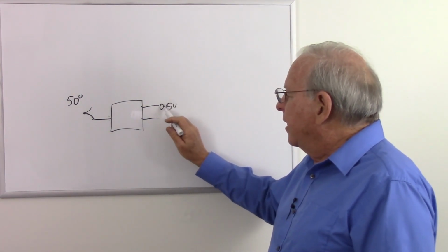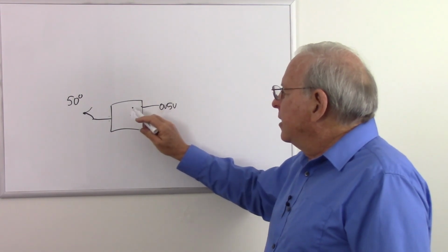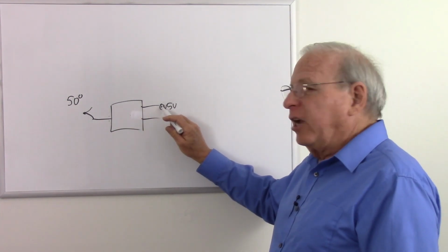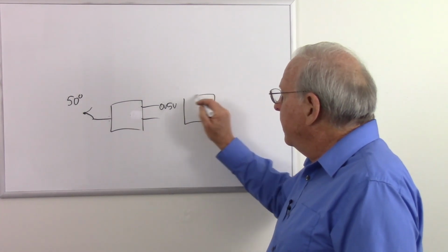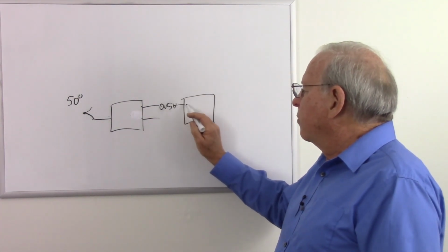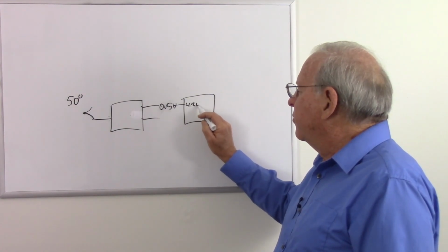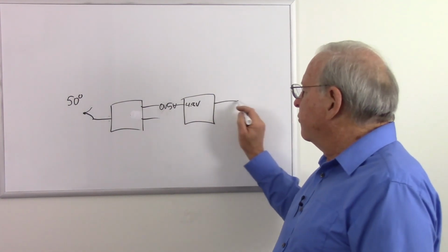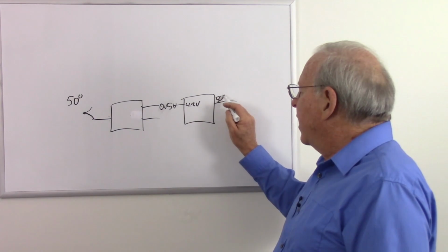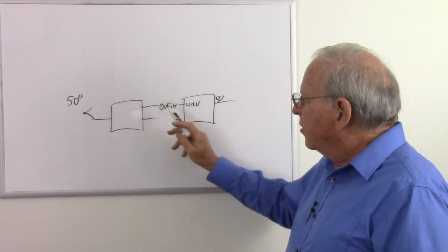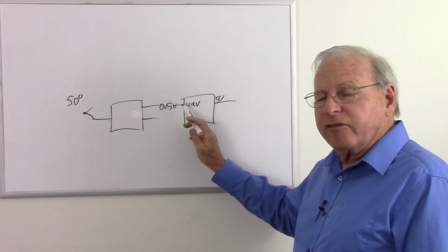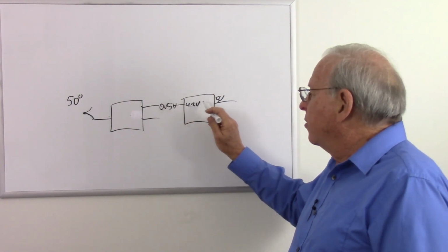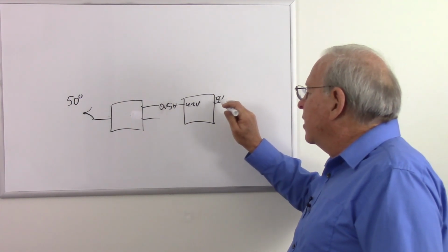So it's very unlikely that some problem with integrity is going to change me all the way from 0 volts to 5 volts. And the circuitry that's picking this up will take, well, what if this goes over here and it's only 4.8 volts? It says, looks like 5 volts to me, and the output's going to be 5 volts, or it's going to treat it like 5 volts. So if the data's changed a little bit going from one place to another in a digital system, every time it goes through a stage, it gets cleaned up.